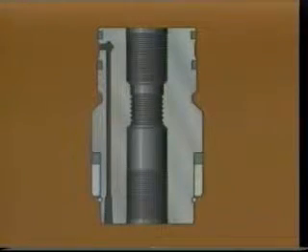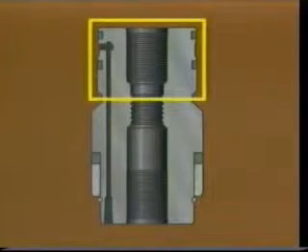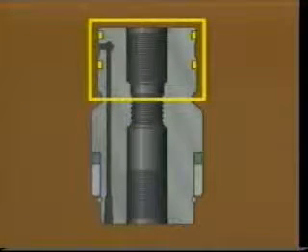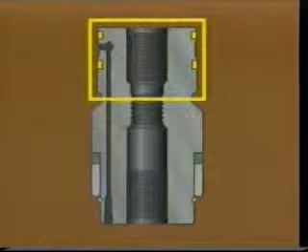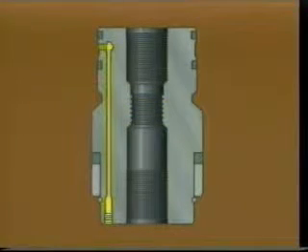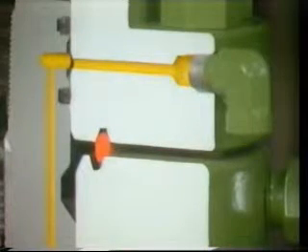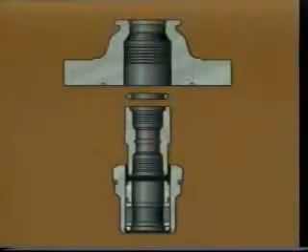In high-pressure or H2S environments, an extended neck with a sealing element isolates the tubing head and tubing adapter flange. A hydraulic supply inlet for downhole control lines is generally available as an option in tubing hanger designs. Surface-controlled subsurface safety valves require a hole drilled in the tubing hanger to hold the control assembly with an extended neck to allow a seal in the tubing head adapter. The hydraulic control line extends to the safety valve in the tubing where it connects to a port.